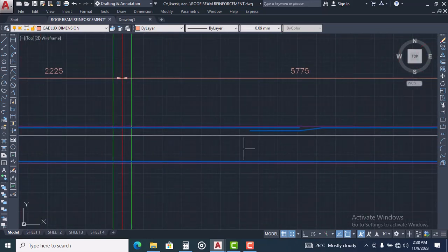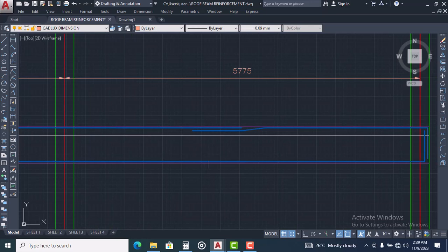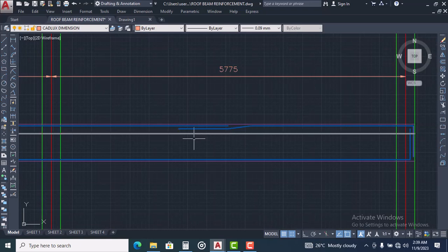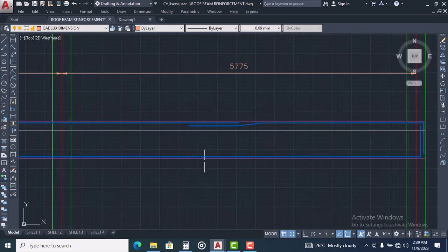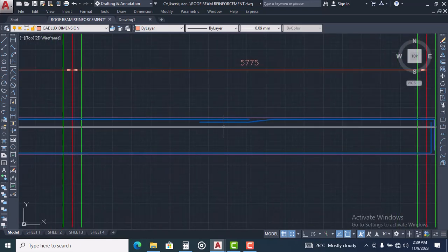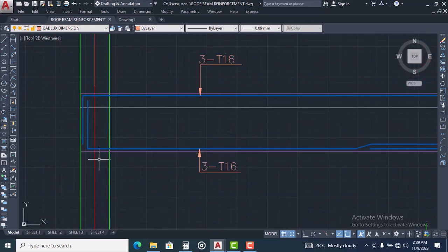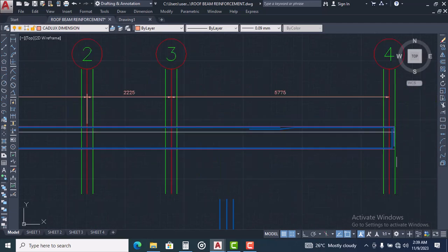Here we did reinforcement bars, which were 16 mm, and we did the lapping. I told you the lapping is 50 times the bar diameter. So this is the lapping. We used 800, which is 50 times the bar size, which is 16. It gave us 800, and we are also to lap here 800 and here 800.